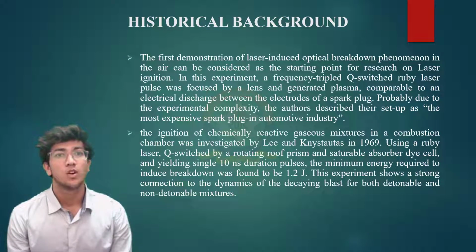Now let's know about the historical background, in which some scientists and engineers had done some experiments. On the basis of experiments, they presented their theory. The first demonstration of laser-induced optical breakdown phenomenon in the air can be considered as the starting point for research on laser ignition. In this experiment, a frequency tripled Q-switched ruby laser pulse was focused by a lens and generated plasma comparable to an electrical discharge between the electrodes of a spark plug. Probably due to the experimental complexity, the authors described their setup as the most expensive spark plug in the automotive industry.